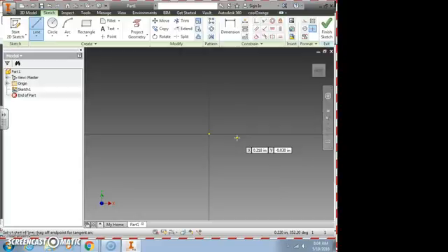When you start off your first drawing, I want you to make sure that you pick the origin. Okay, so you try to tie the view back to the origin at some point. So usually that's just the first point that I pick.